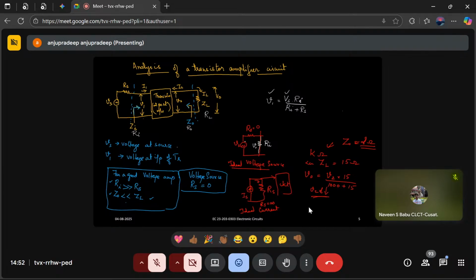So an ideal voltage source would have Rs equal to 0. But getting Rs equal to 0 is not practically possible. So when you make a voltage source, you have to design it to reduce Rs to a minimum value. In your lab, you can see that our function generator, which is a voltage source, has 50 ohms written on it. It means the source impedance of our voltage source is 50 ohms.